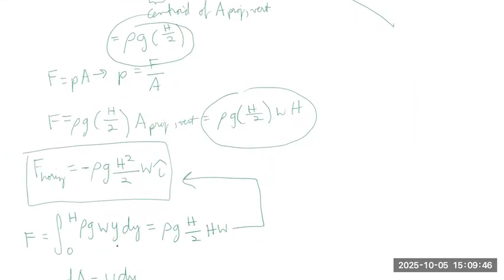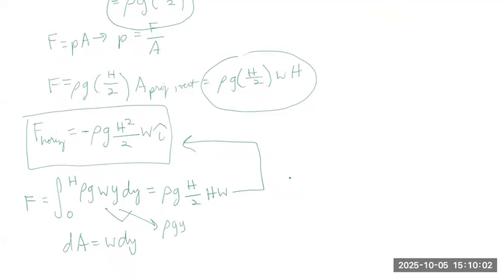However, we now know where these two terms come from, so where does the y term come from in the rho gy? Well, this is just the classic expression for hydrostatic pressure. The density of the liquid and gravity is always going to be there. And the y represents the depth because hydrostatic pressure is a function of depth. The deeper you are, the higher the pressure.